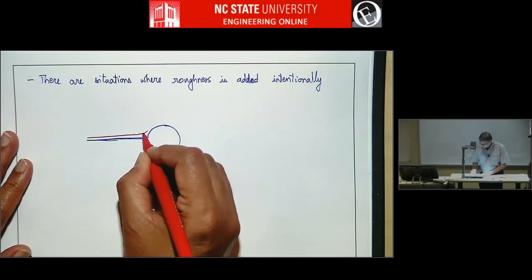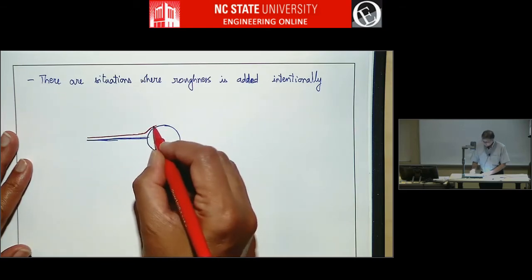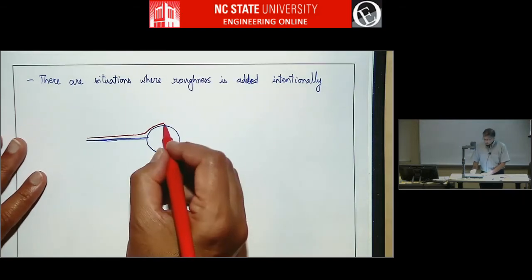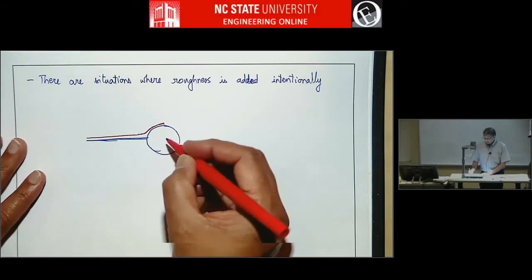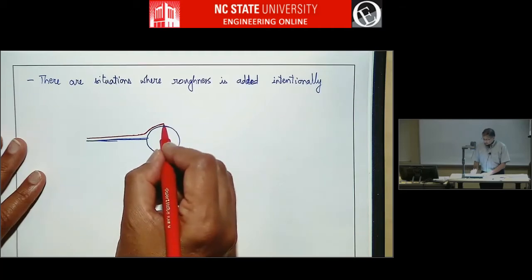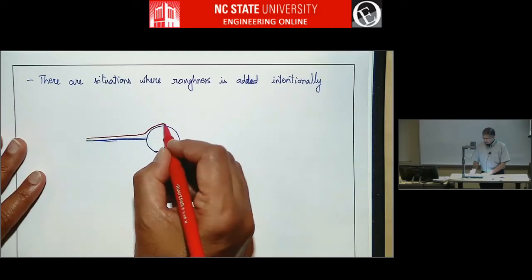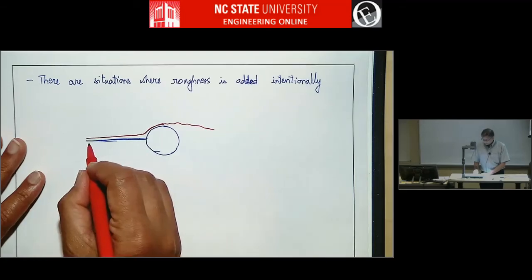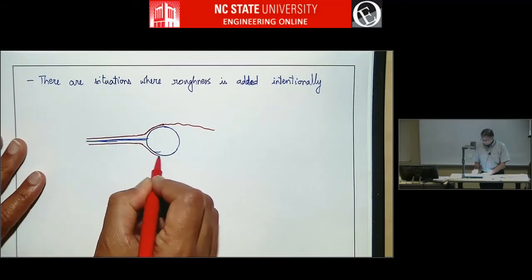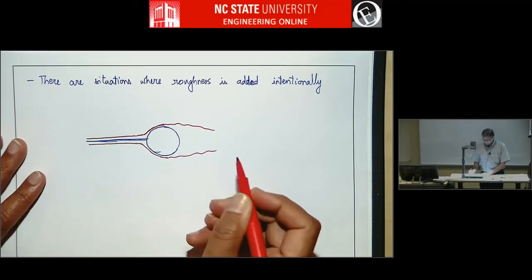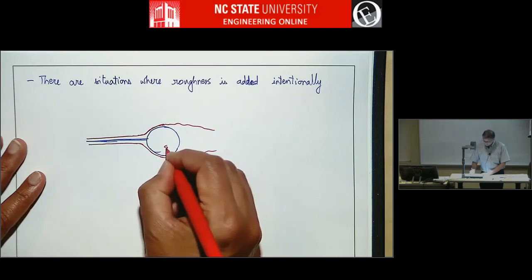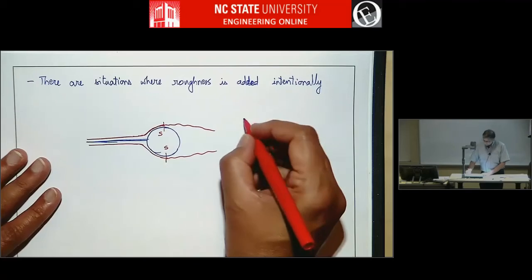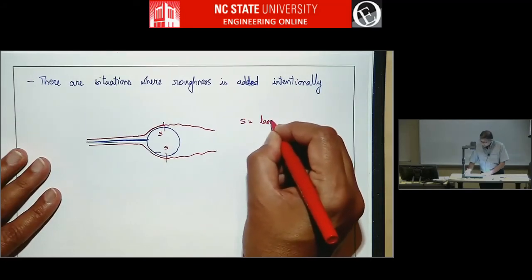So the boundary layer starts off as laminar, and if the Reynolds number is low, it wants to stay laminar, but then when it comes to, let's say, the equator, it sees a big adverse pressure gradient here and it separates right here, forming a big wake. So what happens here is separation, not transition. So S equals laminar separation in this sketch.